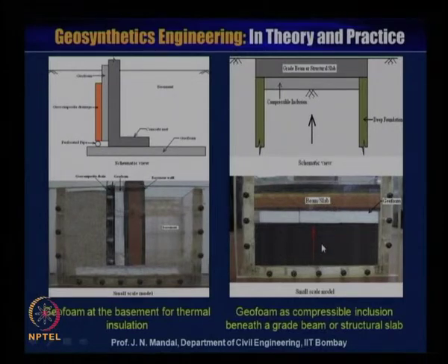Because for the swelling soil there is an upward thrust. So this upward thrust can be minimized by the introduction of the geofoam material, so it will not affect the building, and you can prevent the building from cracking. If you go for the conventional method, then there is a formation of cracks, but here, due to the geofoam material which will act as a compressible inclusion, the building will not have any problem, there should not be any formation of cracks.